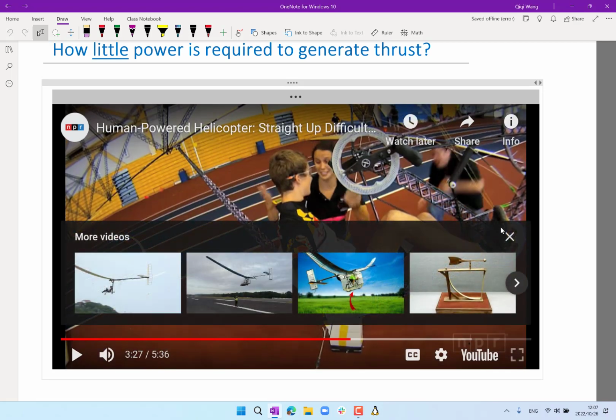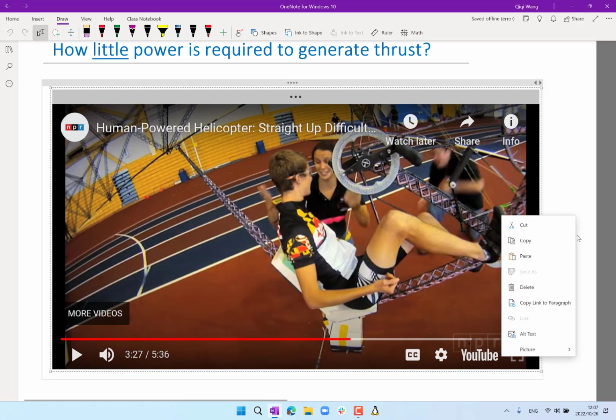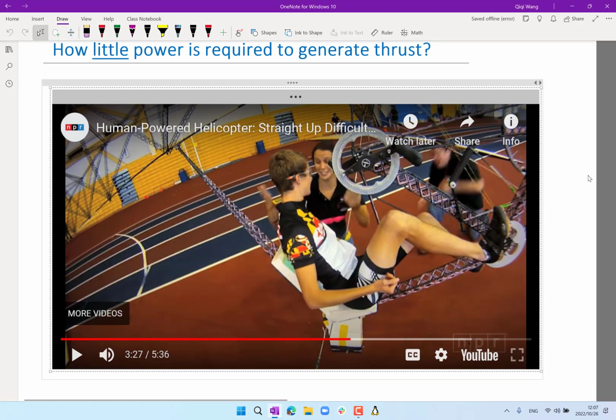Well, one of the interesting things about this flight is that as you also calculated, the induced velocity, the velocity that goes down the rotor plane, I mean, this is 4 massive rotors, right, huge A. As you've seen, the velocity of the flow downward is the square root of T, which is small, because the human is not that massive, divided by 2 rho times A. So the induced velocity, the velocity going down, is also very small.